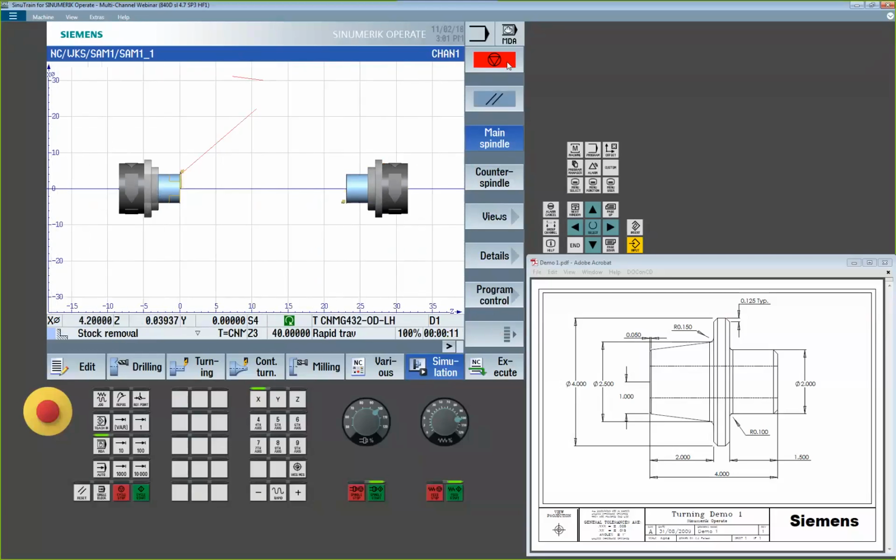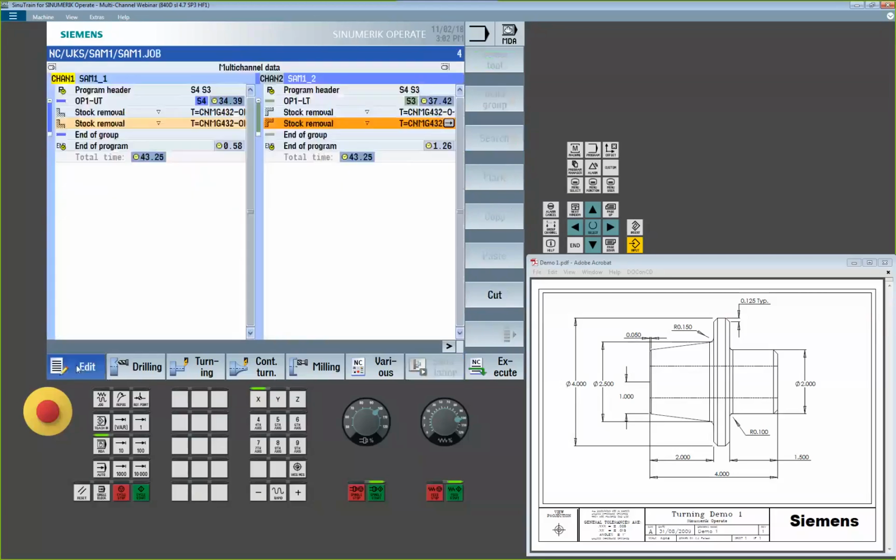There I see the sub-spindle go to its park position. Again, if I want to flip the show path back and forth, I do need to use the little channel button. So not a ton of stuff here, but enough to certainly make it a lot easier to move back and forth between the channels with the simulation. But the beauty here is we're obviously seeing both operations simultaneously. So you can gauge timing and how things are going to start to work on the system.